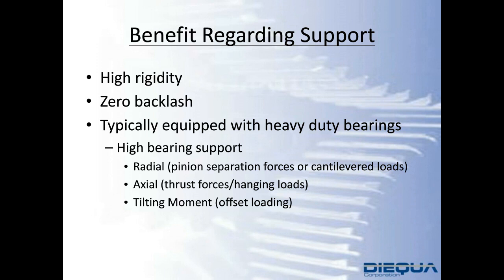You reduce the spring back effect from running very aggressively forward, coming to an abrupt stop, and then having the system want to restore its forces, right? Also, because you're not clamping down on a key, you have a zero backlash connection.